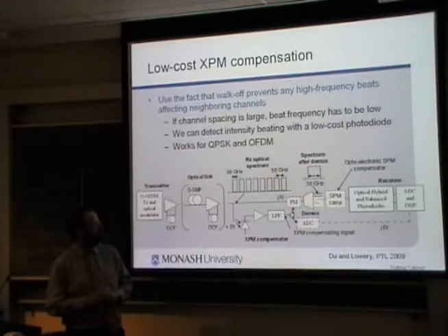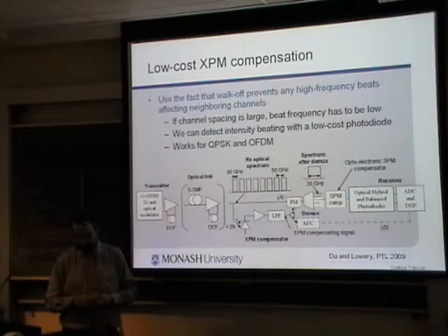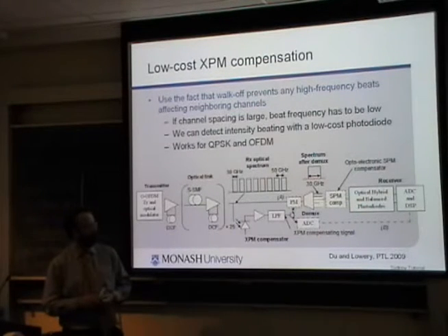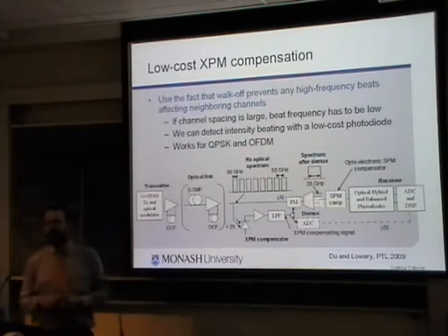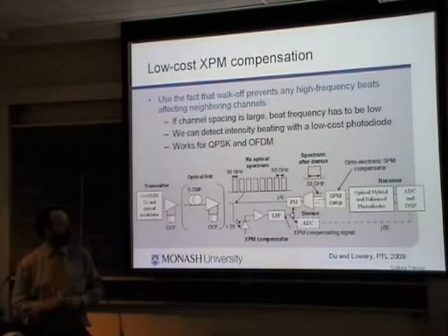One solution is perhaps to do mid-span spectral inversion at the end of the link, which I believe has been done here. Fourier transforms. We believe it's possible to do Fourier transforms that are fast enough to do OFDM in silicon, even non-custom silicon. So these are really fast, running on tens of billions of points per second.